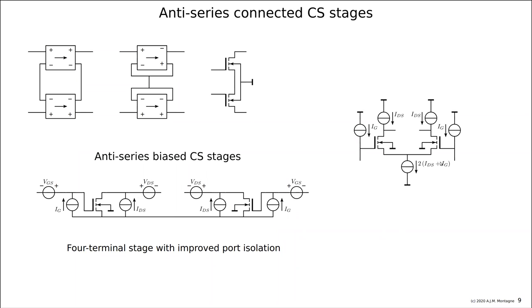And the voltage of the device in this way is not at all defined. So we need external circuitry to define at least the voltage at one node, the common mode voltage at one port, sorry, and the other voltage will then be defined by the device characteristics.